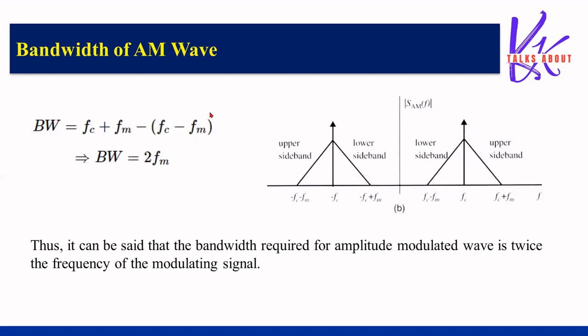So here, whatever you see, the waveform, that is nothing but the spectrum of your amplitude modulated wave, which has both positive frequencies and negative frequencies. Now, let us see the upper sideband. So this is the carrier frequency, and whatever you see here, this is in the positive frequencies, this is the upper sideband, and we have a lower sideband here.